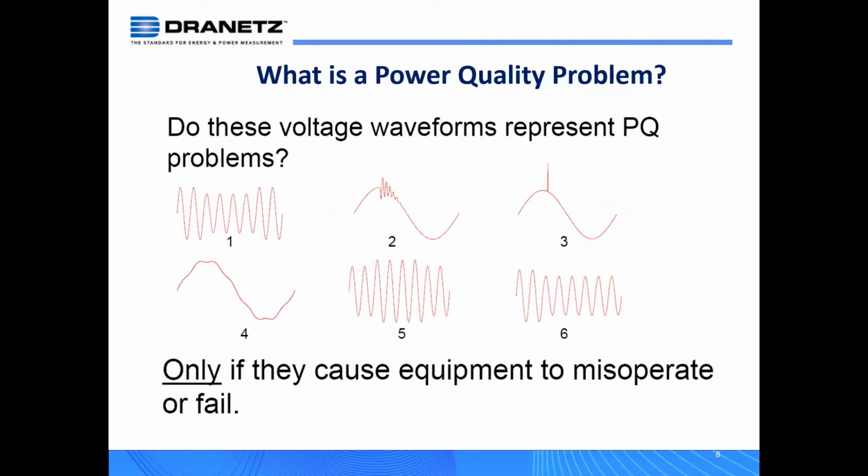And what we see here, and we'll get a further definition of these things in the coming slides, happens to be a sag or a dip. This is a transient, maybe caused by a power factor correction capacitor, which we discussed at Thurman's presentation last week. This is a peak transient, a positive transient. This is waveform distortion here, maybe the harmonics that we spoke about, and we're going to cover at our next presentation. This is a swell or an increase in voltage, and this is a long duration sort of sag, maybe a brownout or something like that.